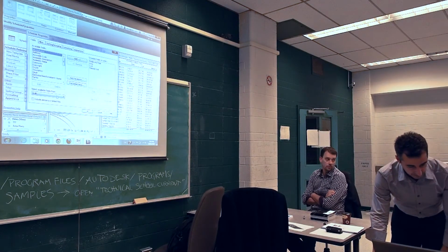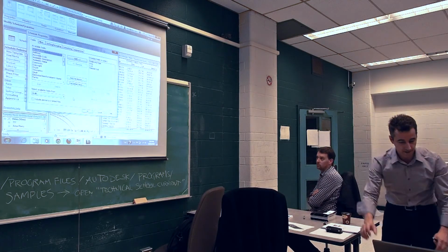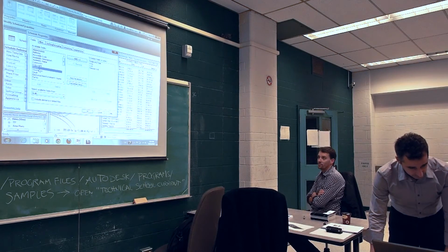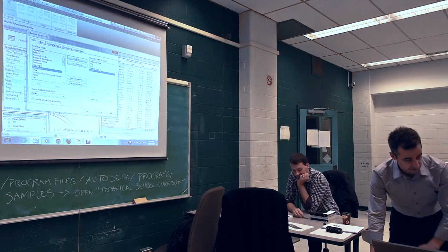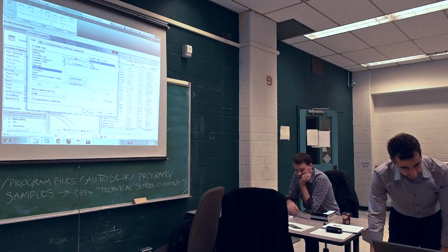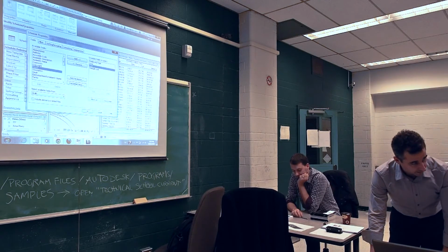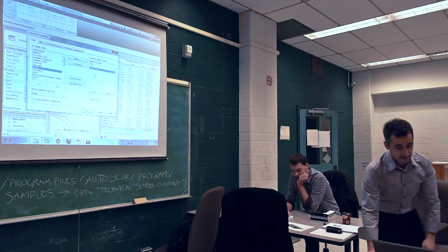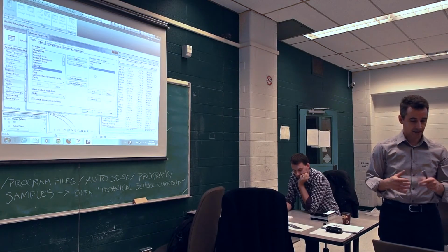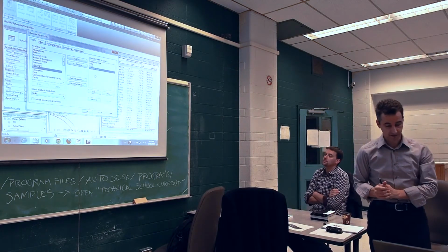If I want to schedule something else, I'll show you how to get there. Out of these fields, I can choose any and click add, and it will be added as a column in my schedule, right? So that's how I added family and type, area, and cost. There is no such thing as material cost. That's a made-up column because I need it. I think I need the total cost of that material.